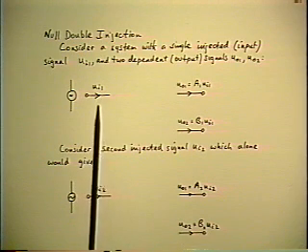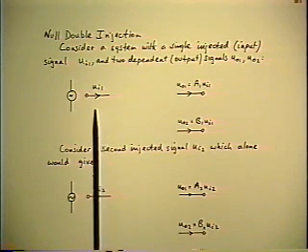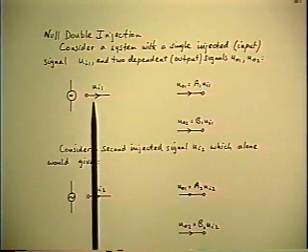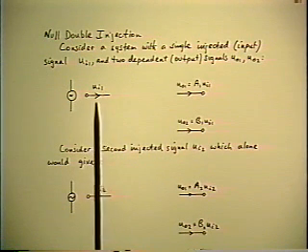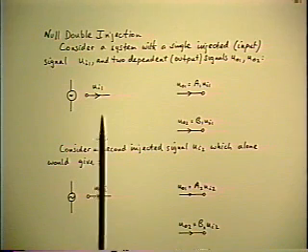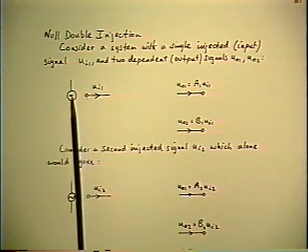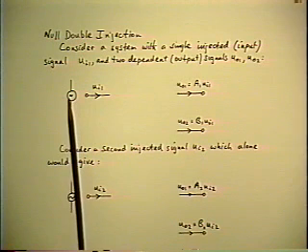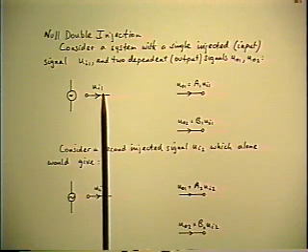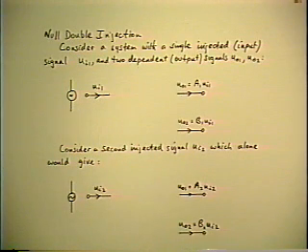What you see right here so far is defining some notation. We have on the left an independent driving signal, U sub I1. I'm using the symbol U because I don't want to call it a voltage or a current or anything. In fact, it could be a lot more general than that. If it's a mechanical system, the independent input may be a torque, for example, or a force. So U is an independent signal represented by a generator in circuit symbol notation. The sub I means input or independent, and the 1 simply means it's the first one that I'm talking about.